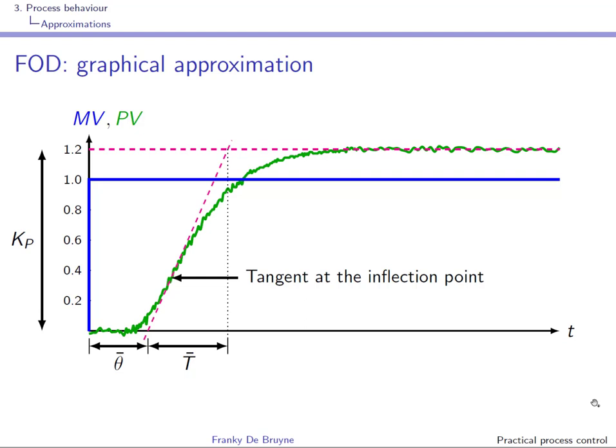So here we have obtained, using experimentation, a unit step response, in open loop, and this graphical approximation method, you'll be able to use it to identify an approximate model for lag time processes, where you have a succession of several first order systems with also possibly a dead time.